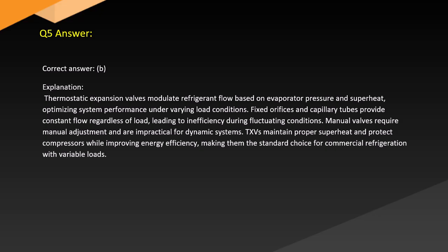Fixed orifices and capillary tubes provide constant flow regardless of load, leading to inefficiency during fluctuating conditions. Manual valves require manual adjustment and are impractical for dynamic systems. TXVs maintain superheat and protect compressors while improving energy efficiency, making them the standard choice for commercial refrigeration with variable loads.